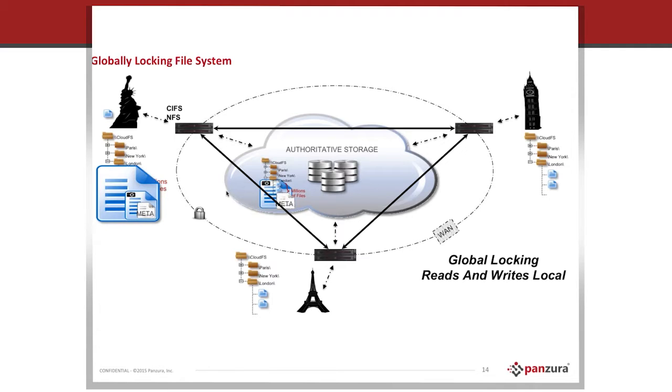You're working on that RVT file there on your desktop. What it's doing, though, is it's very subtly going into the backup folder for that central model. And every time you move objects, you check something out, you check out a work set, you check out an element, it's reading and writing small amounts of data into that backup folder.